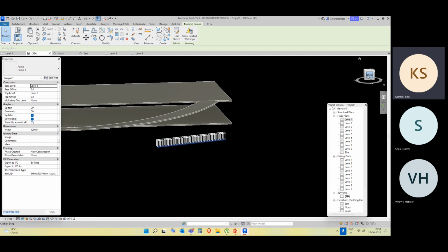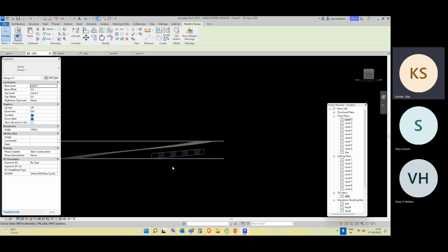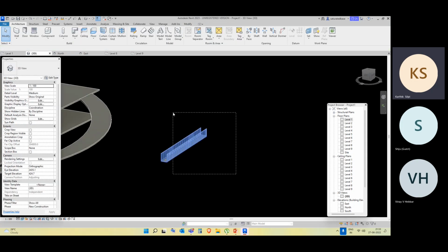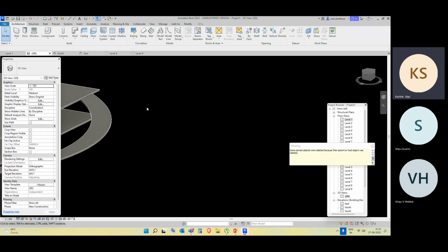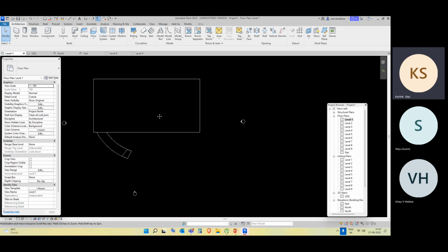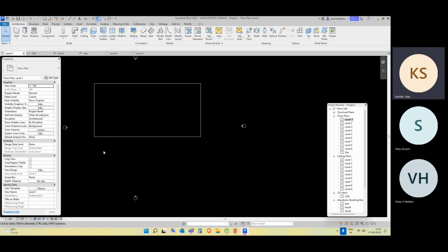So why we are having error is, here you can see with this height, if I'm going to draw a ramp, it is not going to touch the next floor. It has to start from this place. So if I'm going to design in this given environment from that place, it's going to take a lot of space. So this type of ramp is especially useful when you're following design standards and it demands particular design standard in the location, like as I've said, in the hospitals. Okay, so there is one more concept, that is staircase.